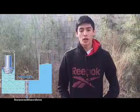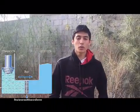Function of a hydroelectric power station. The dam serves as a container for the water in the reservoir that flows through. The pipe leads to the machine room. Upon arrival, a series of gates and grills regulate the flow of the water and act as a filter, preventing material that can damage the machine from reaching the turbine. Water is transported through ducts and tubes, controlled by valves that control the amount of water reaching the turbines depending on the demand for electricity. Then water is discharged through channels.